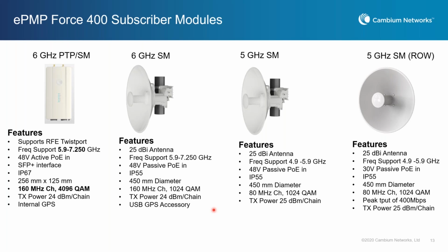In this case, we can use those different sub-channels inside this 40 megahertz channel to send data to different subscribers at the same time. So it's another dimension of multi-user access to the air. We can do it in the downlink to send data to multiple subscribers at the same time, or we can do it in the uplink.